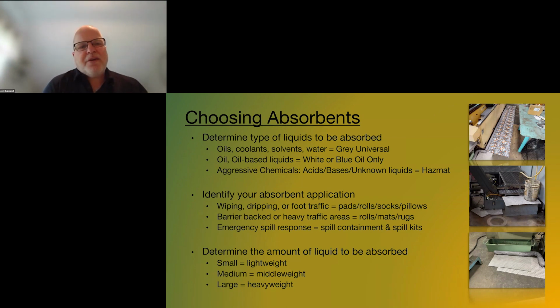There's the whole thinking of choosing the right sorbent. We put together some bullets, and you'll receive this presentation later on. But choosing the right sorbent, it's not a complicated decision. It's just some things to think about. So you want to really determine the type of liquid to be absorbed, whether it's an oil, coolant, solvent, or water. You'd go with a universal gray, oil only, white, or in some occasions blue.